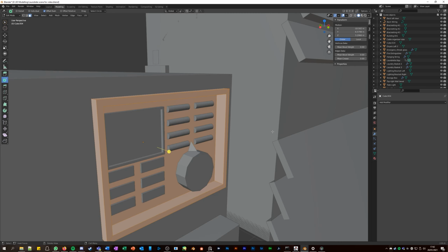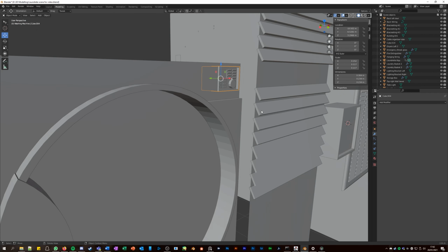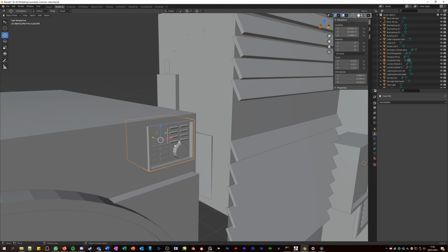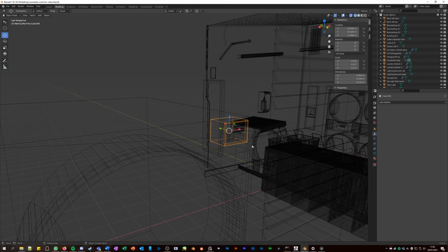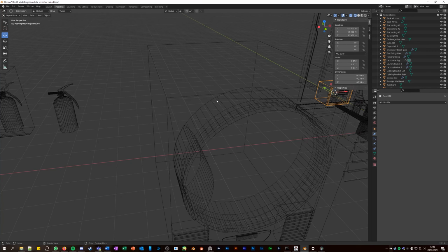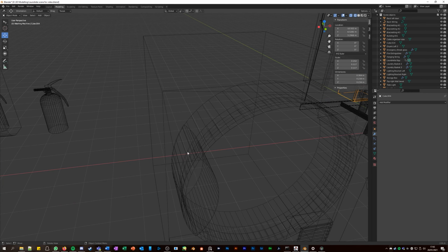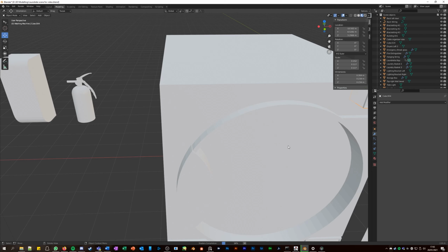Solid is just this normal view, good for modeling. That doesn't have any color or texture. It's just basic. It doesn't take in anything from the lighting. Very fast. And there's wireframe. It cuts out the sides. You can just see the edges of everything. Useful if you need to select a lot through something, or there's stuff inside of this cube, which at the back I can get to if you're looking in solid view. Then there's also material preview, which is a bit slow sometimes. There's so many materials here.